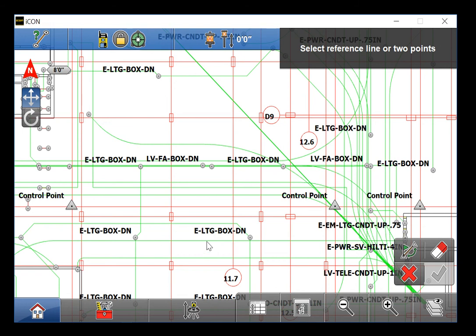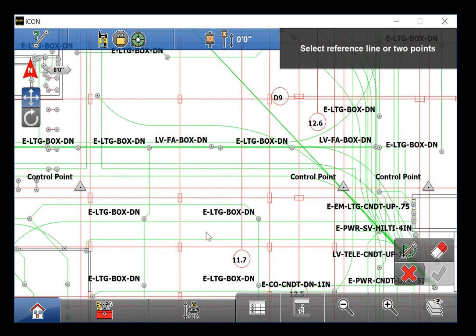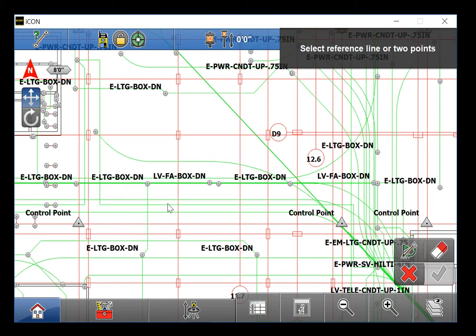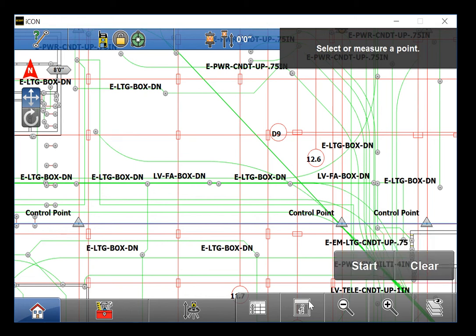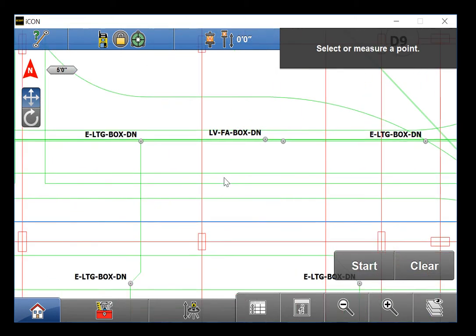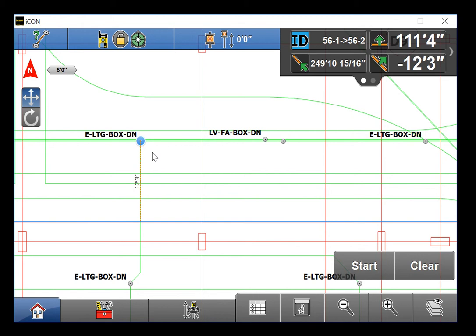For whatever reason, if your total station doesn't have line of sight on the other side of shear wall rebars or column rebars, or if your batteries died and you find yourself in a position where you need to start laying out points with a tape measure, one person with this tablet could simply select the control lines, walk to the area they need to lay out, extract the information, and start sliding their tape measure out to hit multiple points, regardless of the point's type.